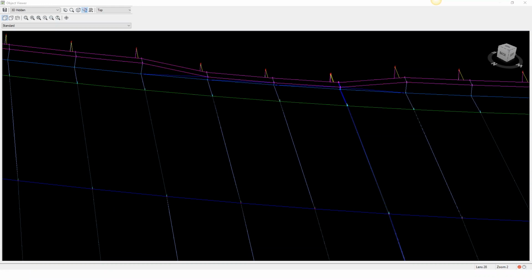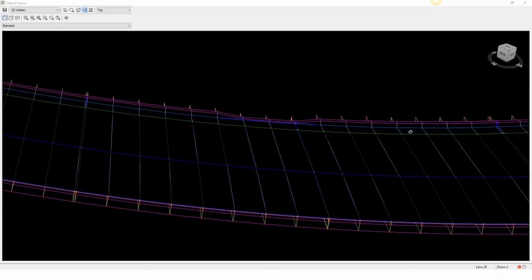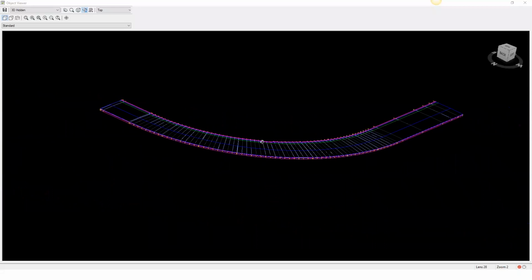I don't want to come in and say set to elevation because my curb may be at an 800 foot here, but it's at an 800.2 here, and then an 800.25 here. It's hard to set a target elevation off of that. Setting a profile view for the elevation is much better. But yes, setting that to 0.5 down to 0.1, 0.05, whatever you want your lip to still be, and then back up, it works on there. So that was two examples that I used.